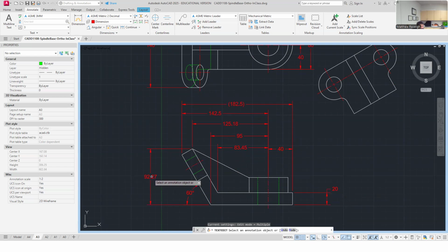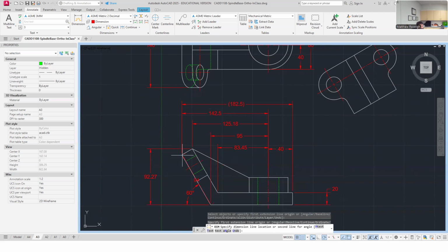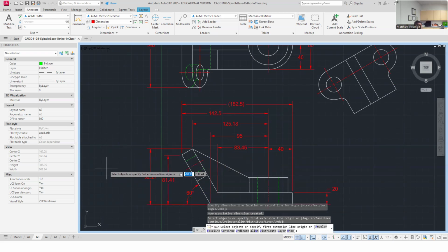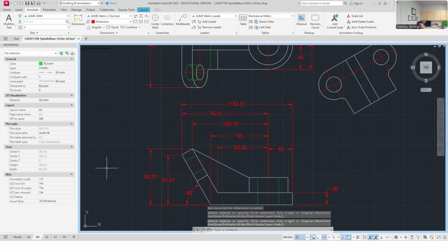I'm going to keep it. It's actually a nice control, potentially a control, because it's off the bottom datum. And the only one I'm lacking is this one. And so I'm going to pull it from bottom to up here, right? I'm going to pull it like this. And I'm going to pull it linearly like this. It gets to be kind of cumbersome and it looks kind of busy because that's kind of like XY point to point coordinate dimensioning.